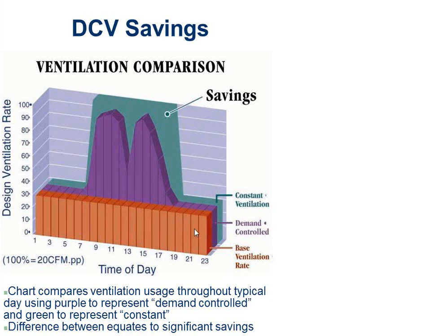Boom. Then at nighttime, it really kind of cycles on and off, because if you didn't already know it, on a normal air handler, the outside air damper on a rooftop, every time you call for heating and cooling, that outside air damper goes wide open. Or not wide open, it goes to ventilation position, because the rooftop has no idea that it's not ventilation time. If you've got an advanced DDC system that's taking direct control of the actuator, that is often changed and you make it 0 CFM.